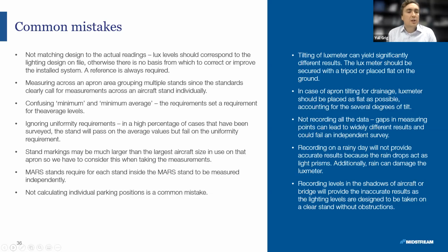Another common error is confusing the minimum and the minimum average. Just recently, we've been talking with a customer who still insists that the requirement is that the minimum should be above 20 lux. And we are explaining that the standards call for a minimum average. So the requirement is therefore average levels. It's not a minimum of 20 lux, it's an average of no less than 20.